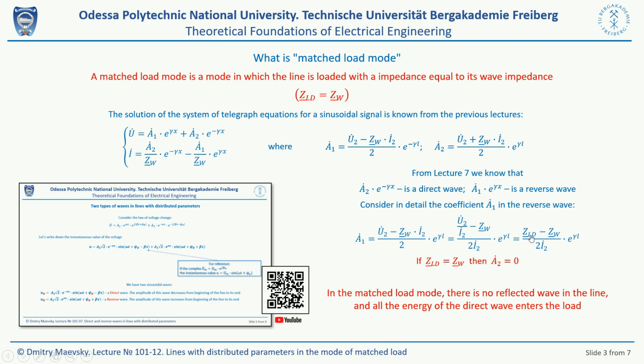Therefore, in the matched load mode, the numerator of this fraction is equal to 0. Consequently, the integration constant A1 is also 0. This means that there is no reverse wave in the matched load mode. This is the most important property of the matched load mode of the lines.